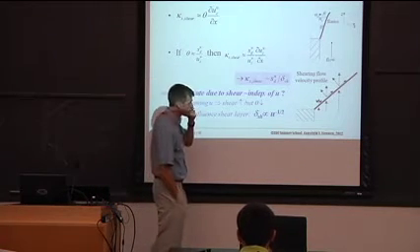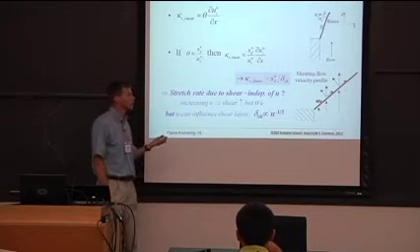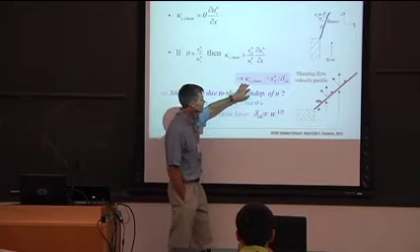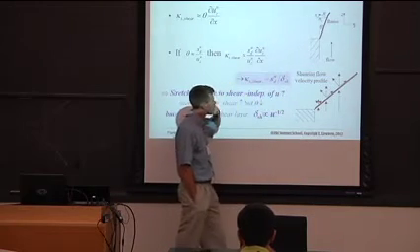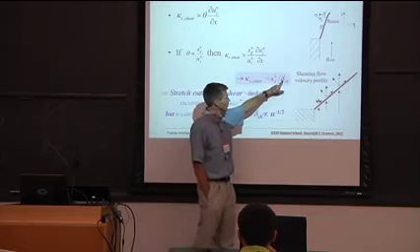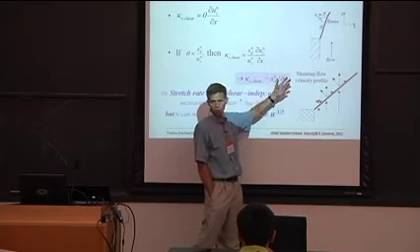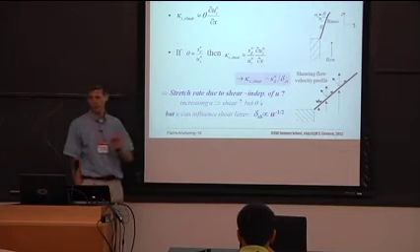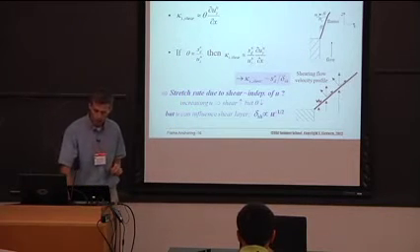But you might ask, well, it's a pretty typical observation that as I increase flow velocity, flames blow off. And this is saying that it's independent of velocity. Well, in fact, there is a velocity dependence buried in here. Boundary layer thicknesses, for example, a laminar boundary layer thickness is 1 over square root of u. So there is a velocity sensitivity, but it's a square root of velocity sensitivity.